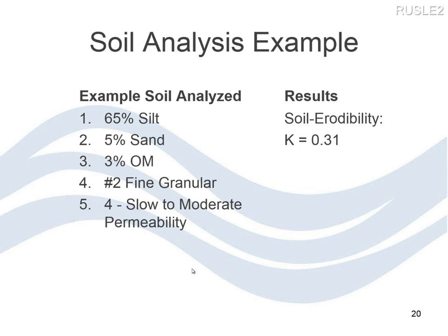Organic matter serves as a kind of glue to stick those soil particles together, so it holds the soil together better and causes it to be less readily detached. That's the broad connection between organic matter and soil erodibility.